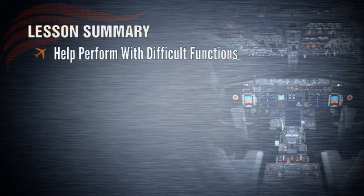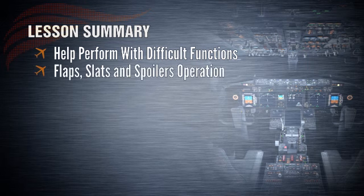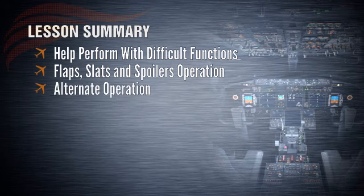It's important to understand secondary flight controls properly because they help the flight crew in performing functions that are otherwise difficult to do on their own, such as allowing for steeper rates of descent without a significant increase in airspeed, and other functions that we've described during this lesson. We discussed the different ways of operating flaps, slats, and spoilers, what their redundancy systems were like, and what kinds of mechanisms are available to protect them in case of any unforeseen condition. In the event of hydraulic failures, we also discussed their alternate methods of extension. It's important to keep in mind that alternate extension of leading edge slats may take as long as a minute under some cases.